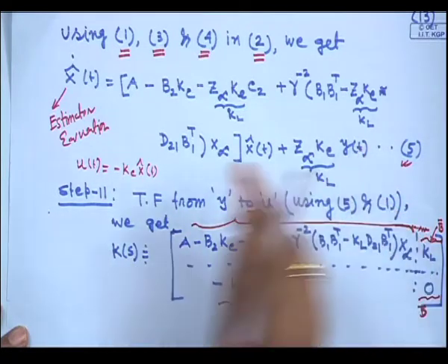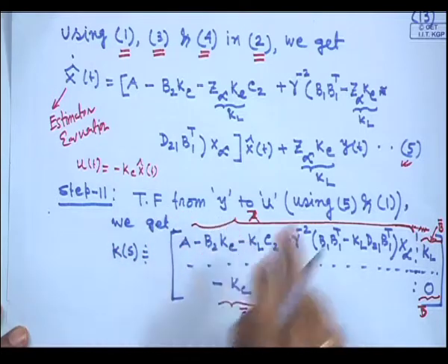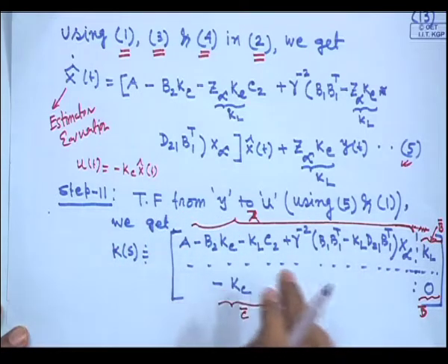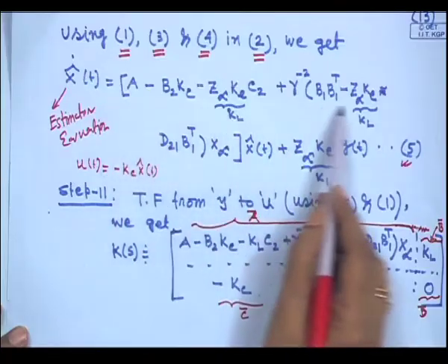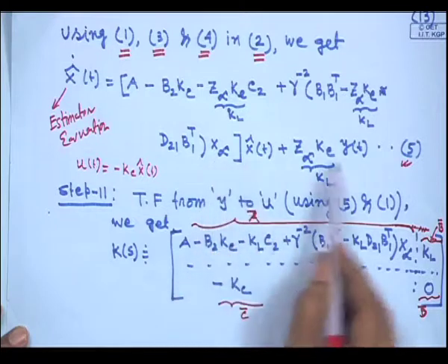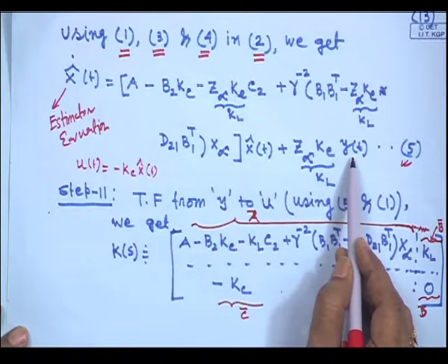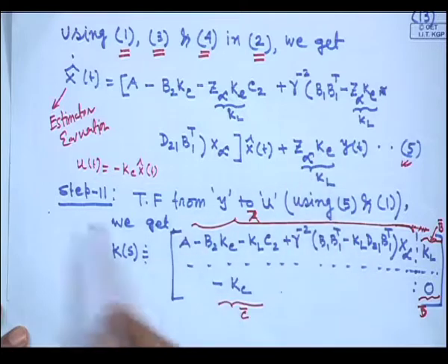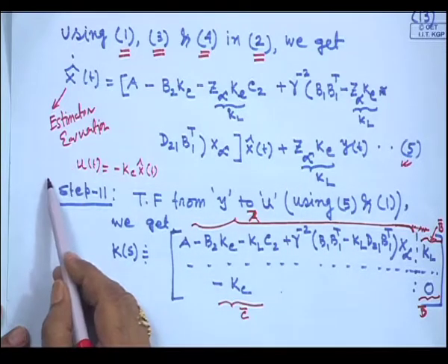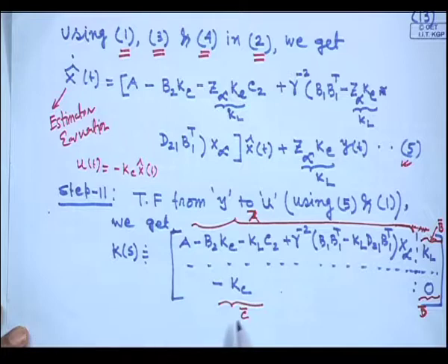What is it? It is something like x dot is equal to A x plus B u, y is equal to C x plus D. Find out the transfer functions. So, in our case this whole thing will be our A. y of t is the input to the controller, so this is our B, our output is u of t. So, this will be our C. It is C here, B here, agree, and D, there is no D term here, D is 0, D bar, and the whole thing you can think of as A bar, B bar, all these things.